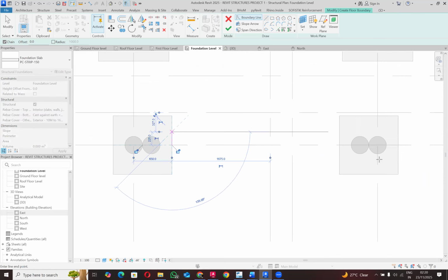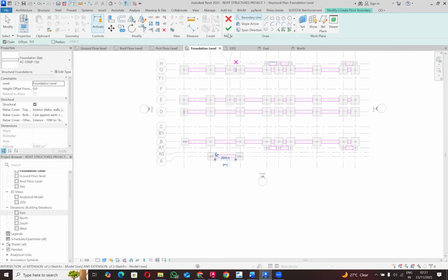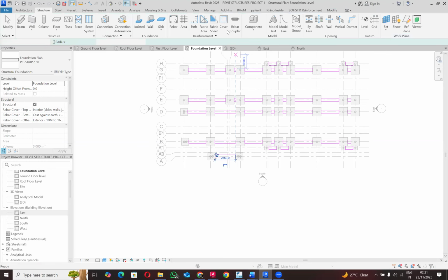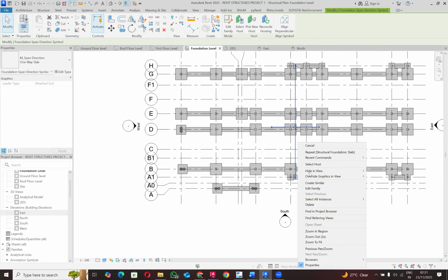55 for the horizontal. Sometimes when you're casting on site, you have to have a strip casting methodology where you're casting all the horizontal strips first before you come and do the vertical ones. So you're doing it day by day. Now we have everything for the horizontal done, and you can just take all this masking and delete it.